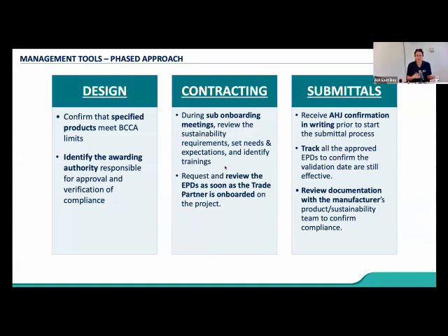For example, if you have to procure compliant structural steel, and at time of bid the subcontractor says we're good for complying with that Buy Clean limit, but then they come back and say we're going to get it from China, I would want to make sure that they are providing EPDs as soon as humanly possible. Can you really get it from China and have it be compliant with Buy Clean California? Prove it to me. Show me the document. Because otherwise, if you're planning on a lead time that's 8 weeks long for this material, and in reality it's 20 weeks long because you're procuring it from an entirely different country, we need to adapt to that as general contractors.